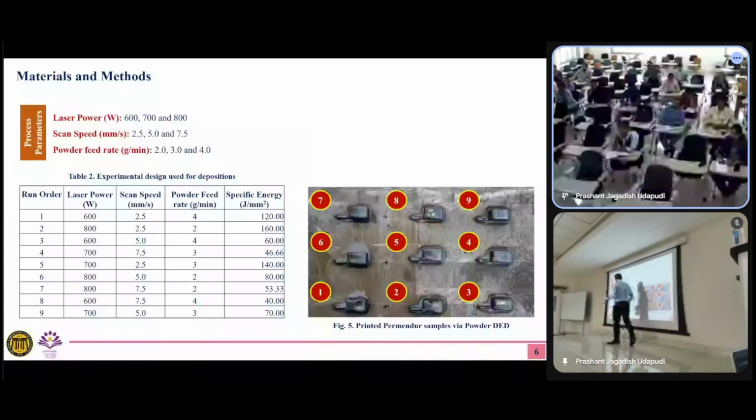But the problem there was we could not establish a pattern. Usually if you increase the laser energy, the slope decreases or increases, right? That's a right pattern. If we establish that, we now know exactly how to tune the properties of materials, right? By just changing the energy of the laser or changing the feed rate or scan speed.